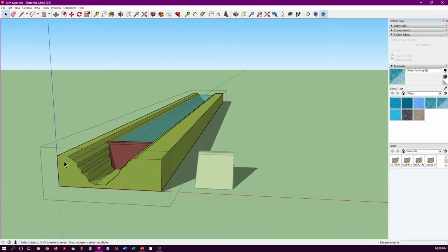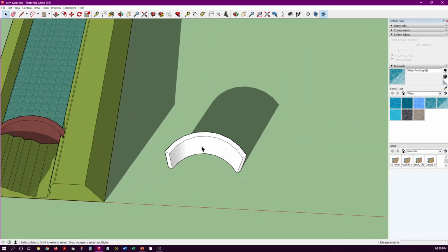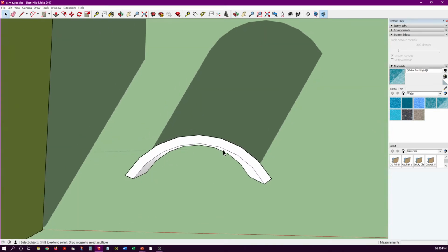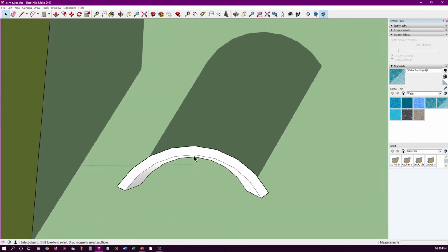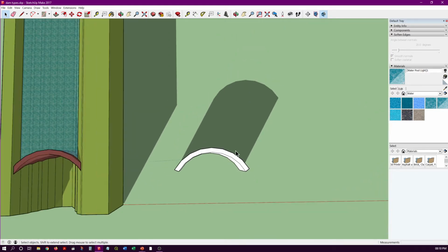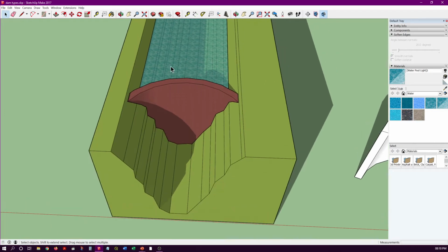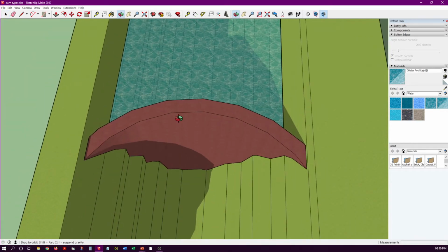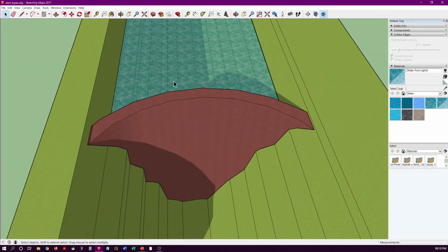The next type that we can discuss is an arch dam. An arch dam works with the same principle as an arch, where load is applied, and through the arch the load is transferred through compression to the supports. Similarly, in an arch dam, the hydrostatic force of water behind the dam will be transferred to these abutments, or the banks of the river valley, and in this way the arch dam will work.